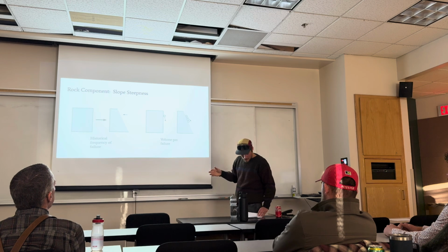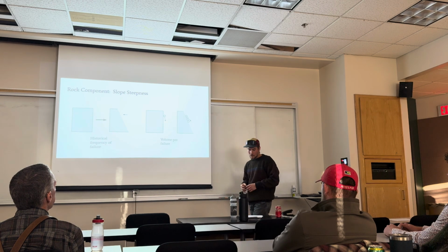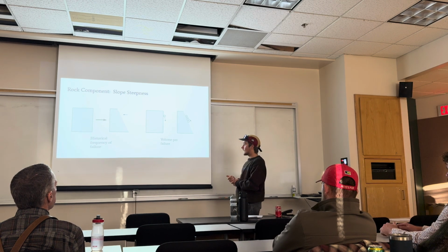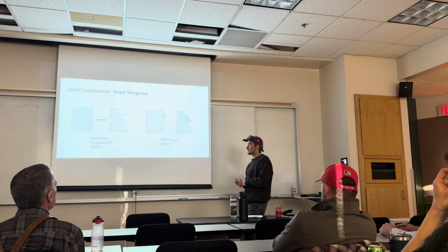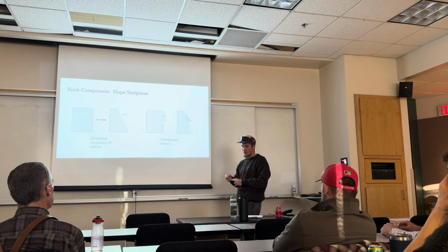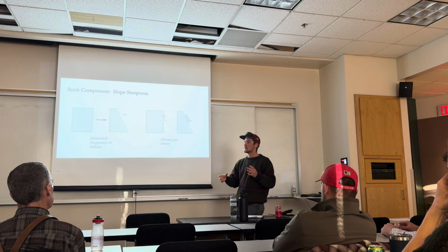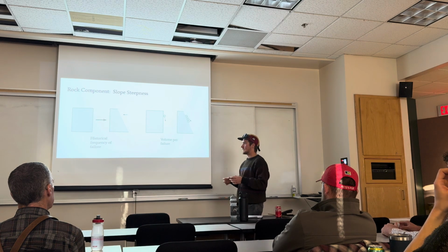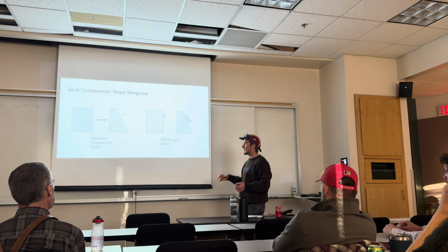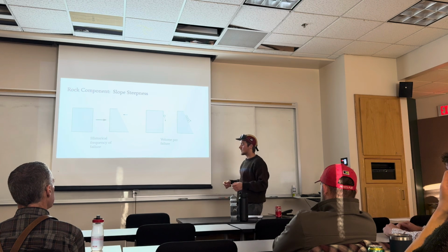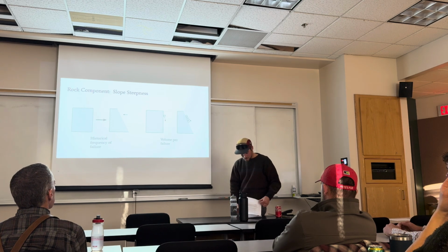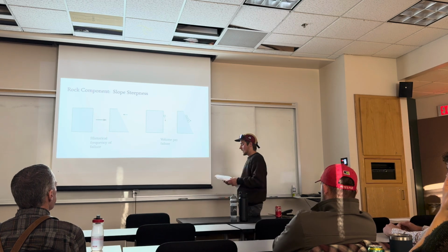So what this means is that we're looking for a mid-ground slope that would produce the largest volume of rockfall as well as the greatest frequency of rockfall. And if not by snow incorporation, I'm talking about the volume per event. It's still, rockfall matters because it's incorporating the ice and percolating water that refreezes into the rock glaciers themselves. So that's understanding the rock component of headwalls.